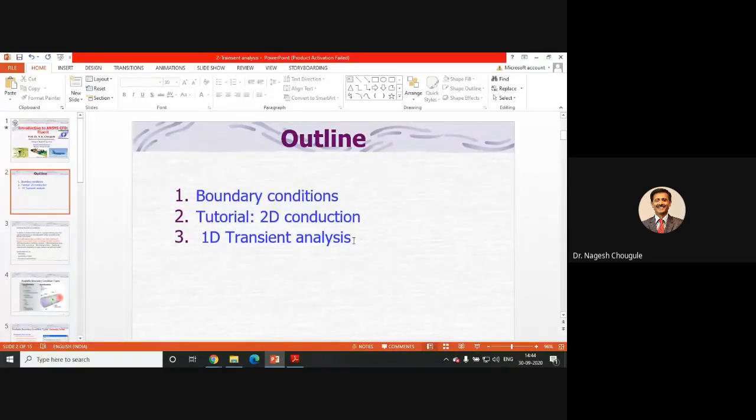Normally, in a standalone simulation, we run one simulation, and for the next simulation I change the velocity and run again. Instead of such iterative operations, you can define it as an operating parameter, simply give the range of the parameter and the step size, and the rest of the work will be done by the ANSYS software.